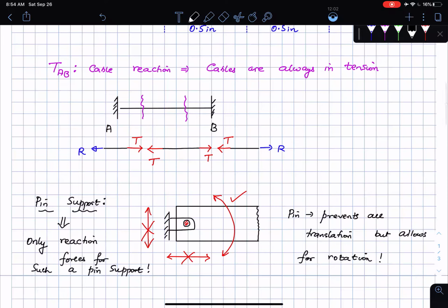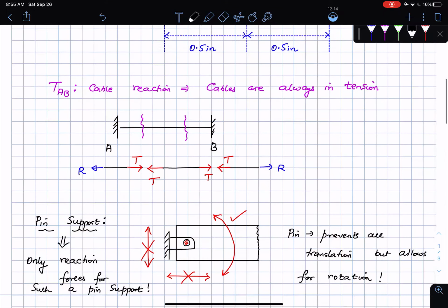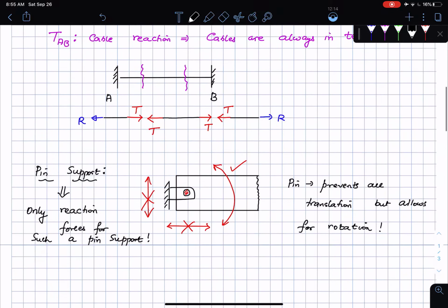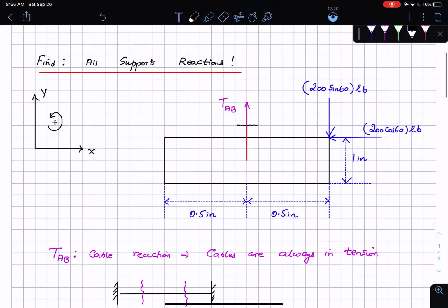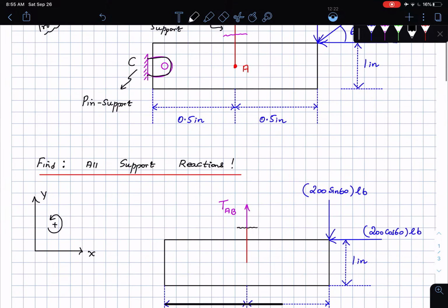Okay. So I come back to my free body diagram. Once again, you see if I have a pin, I cannot move it horizontally. I cannot move it vertically, but I can think of this little piece here trying to rotate about that pin. If the pin is very rusty, I'm ignoring friction and so on. So there are some assumptions that I'm making here. I'm ignoring the weight and so on, but I'm still able to rotate it. But I'm not able to translate it. So I want to list the assumptions here very quickly.